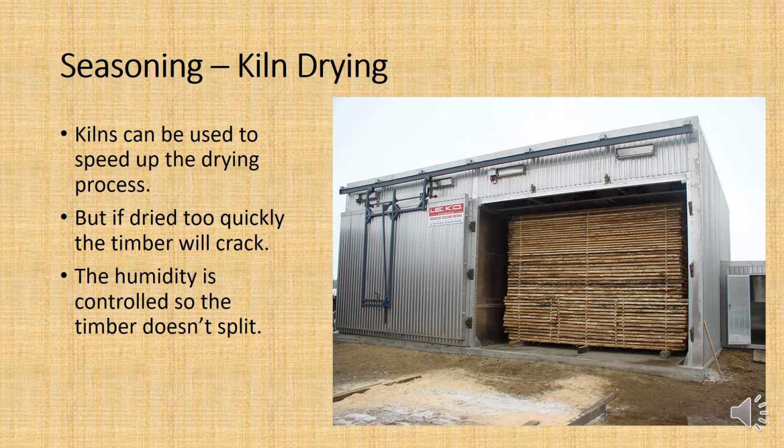Now, you can't just crank up the heat. You can't just turn it up to 200 degrees Celsius and think, "Oh, I'm going to dry it really quickly." Well, first off, if you put the temperature up that high, you're actually going to get the wood catching fire, and you're going to create a big fire. You don't want that.